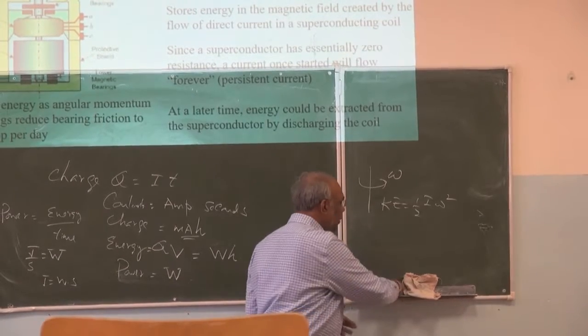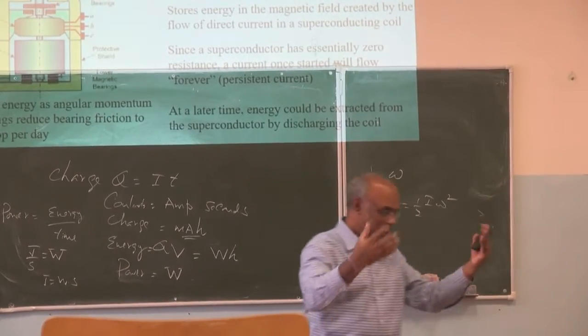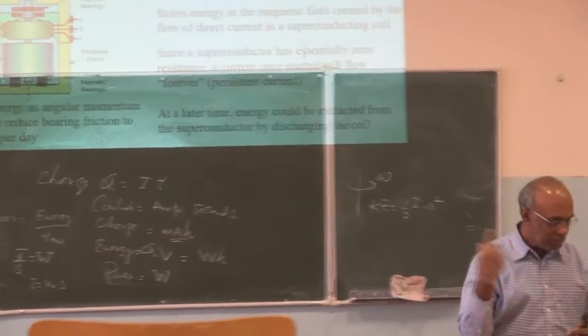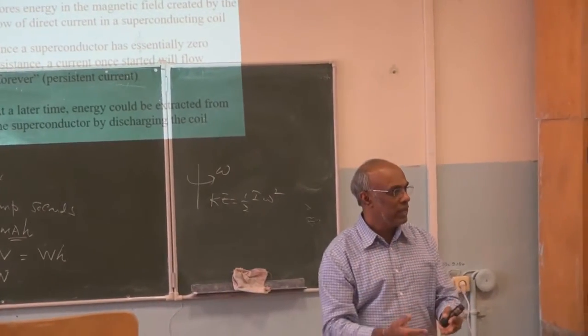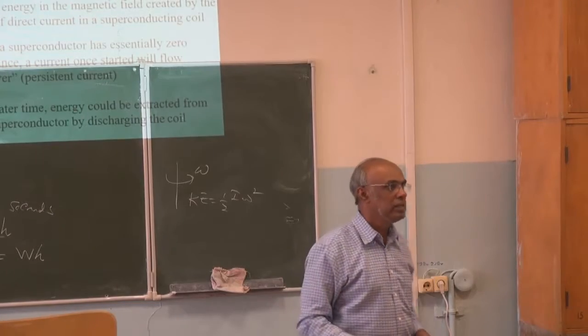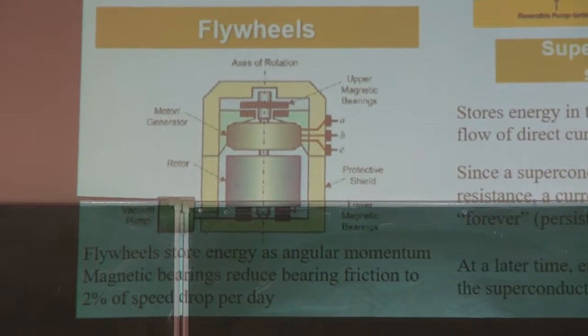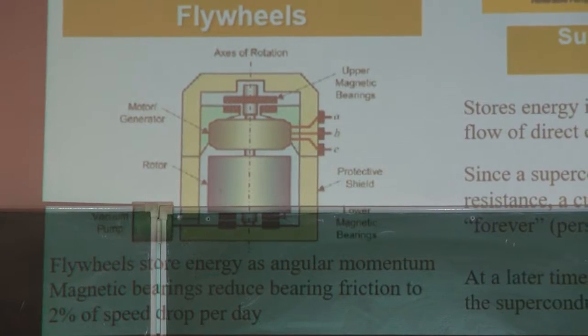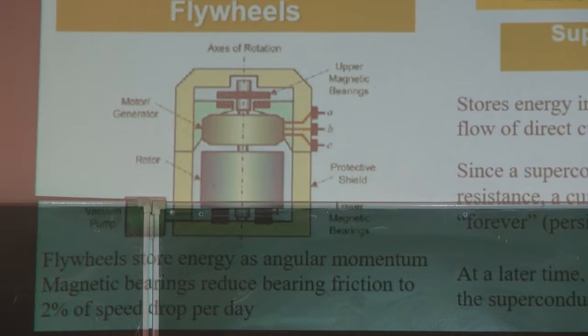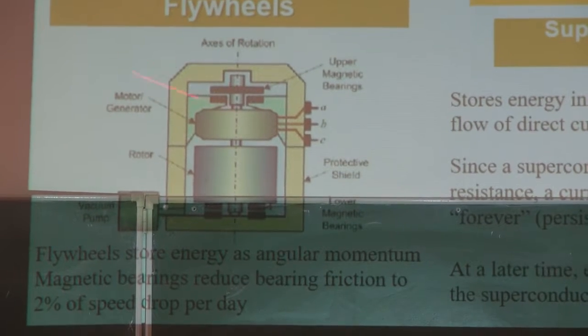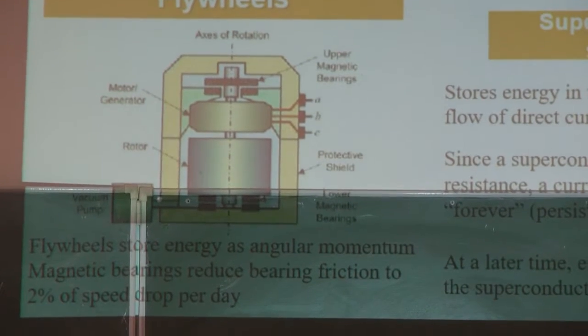This way, suppose you have something, you can make this flywheel store that energy using this kinetic energy. But that has a lot of other issues. You need to have good bearings, otherwise they will dissipate energy, right? So some magnetic cushion, all these things. These are commercially available flywheels already.